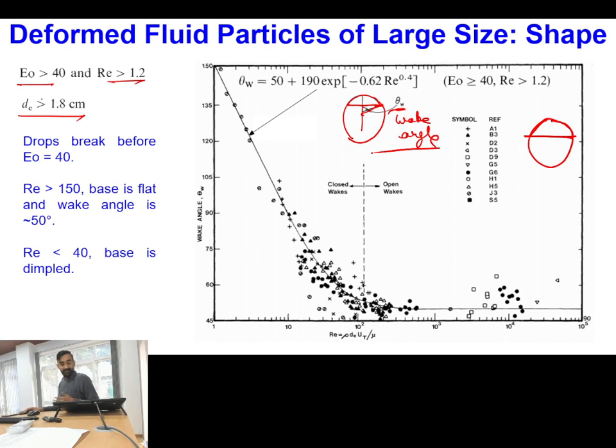Here, the way we had aspect ratio earlier, here also we can calculate aspect ratio, but majorly up to what extent this sector of sphere is extending, that is defined by the wake angle. If you see the value of wake angle, this is the Reynolds number of the particle corresponding to terminal velocity, so ut over here is terminal velocity.